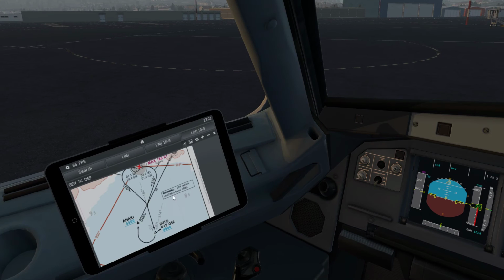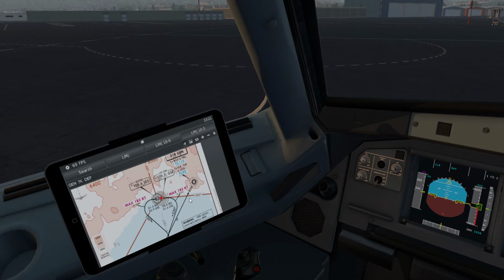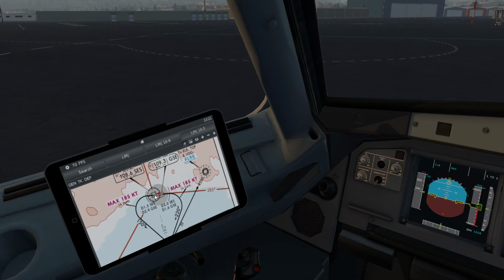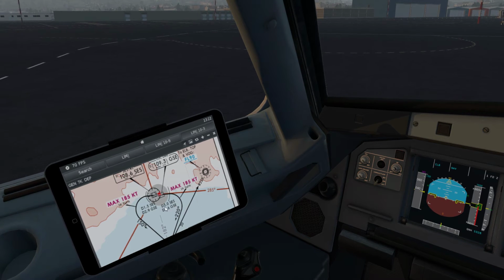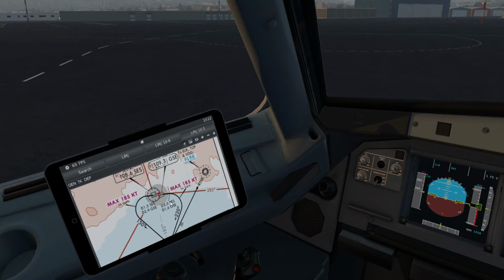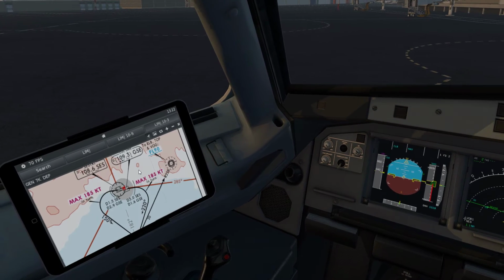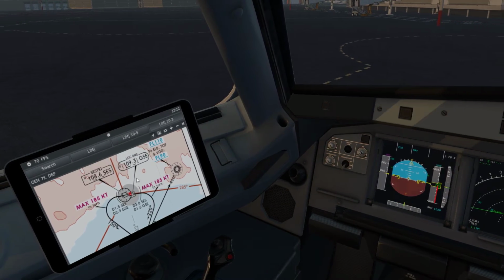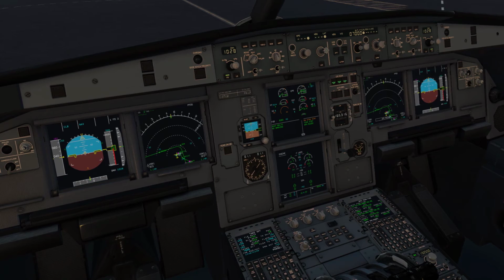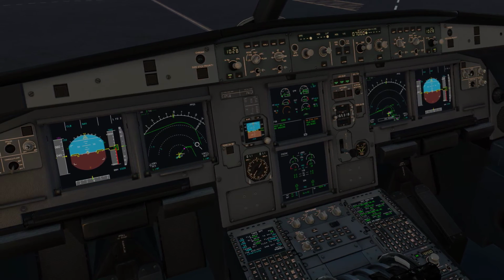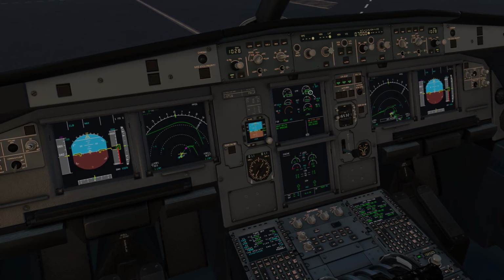Also, let's quickly talk about this one. So we will start runway 10. We'll go straight. We will make a turn at 1.6 DME from GSE or 3 DME from SES. Actually, what we can do, I can show you a little function of the Taurus, which is a really nice function. Before I do that, engine 1 is available, so...